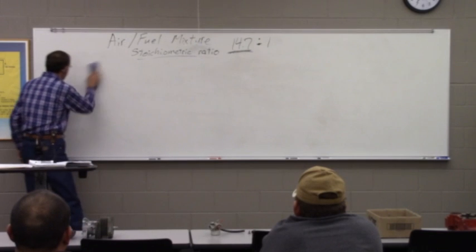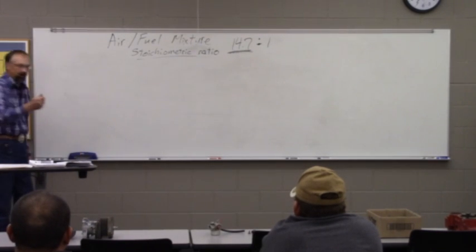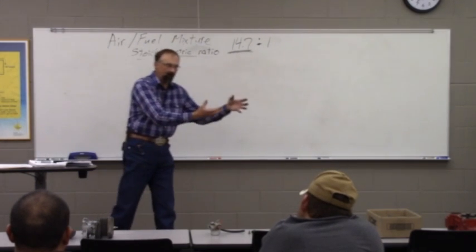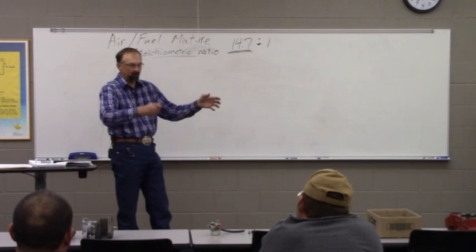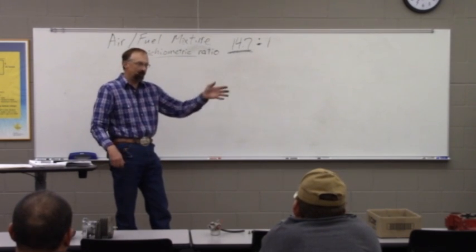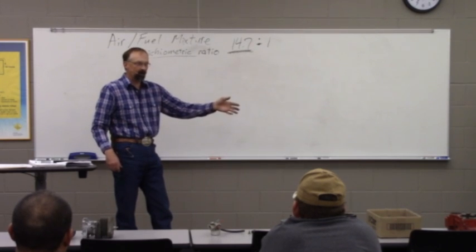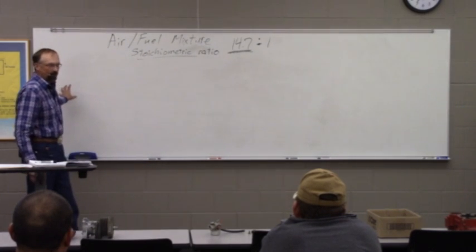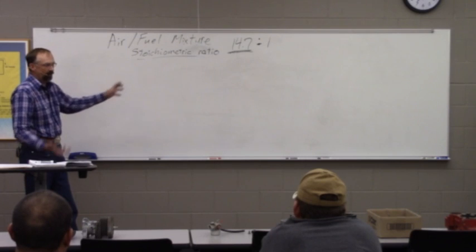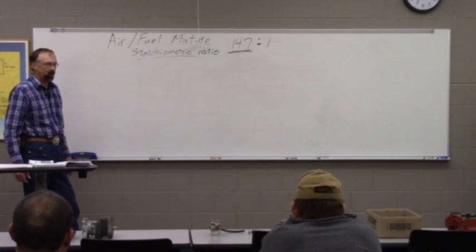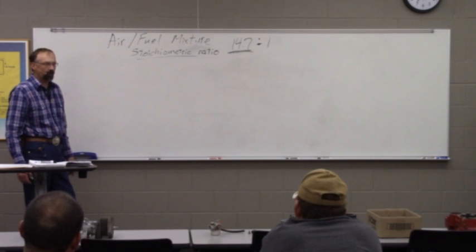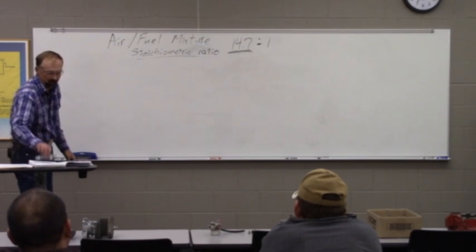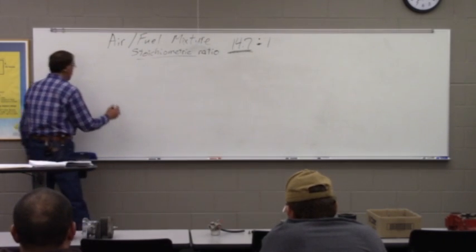Now, in our vehicles, we will have what we call an ignition switch. And where that name came from is the system that ignites the fuel. When we turn that ignition switch to the off position, we're killing the system that ignites the fuel. Now, in the computerized fuel injection systems, we're also shutting that off. But of course, in the carbureted systems, we weren't shutting the fuel off. We're just shutting off the source of spark that ignited the fuel. So ignite, ignition, similar terms.